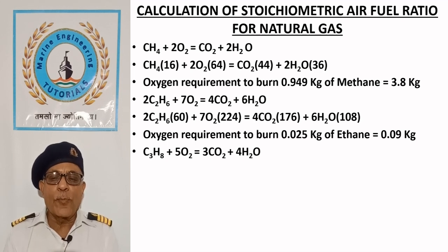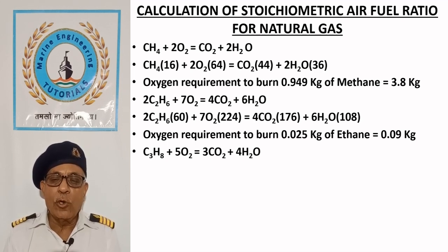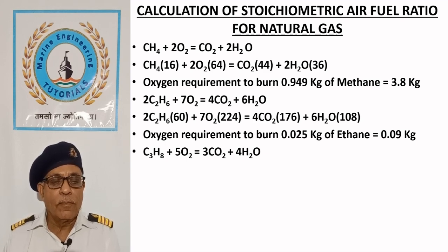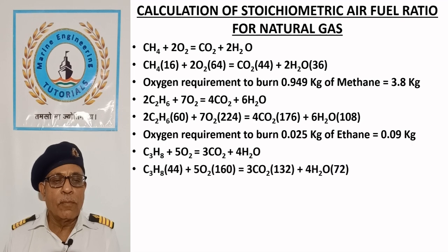One molecule of propane burns with 5 molecules of oxygen to form 3 molecules of carbon dioxide and 4 molecules of water vapor. Substituting their atomic weights in the equation, we can say that 44 kg of propane combines with 160 kg of oxygen to form 132 kg of carbon dioxide and 72 kg of water vapor.